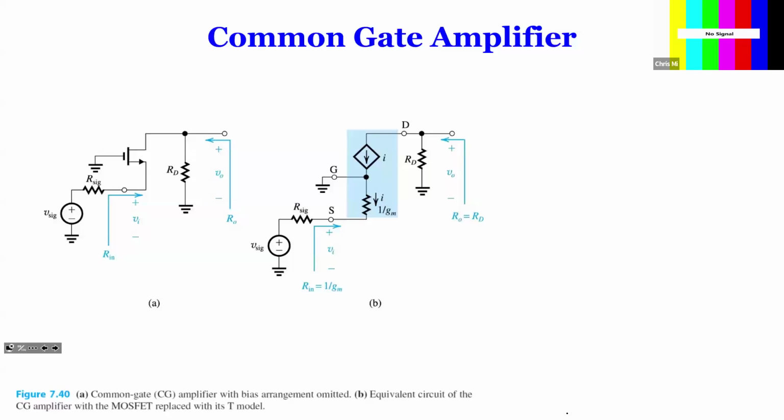So for a circuit like this, I've mentioned many times that we actually neglected the DC voltage. So this is kind of a small signal model already. It's just we didn't draw the DC voltage. If you draw the DC voltage, it will be here, like RD is connected to DC. But for small signal, VDC is ground, so RD is connected to ground. So you gradually get used to this type of drawing. It just represents the small signal, neglecting all the DC variables or DC parameters.